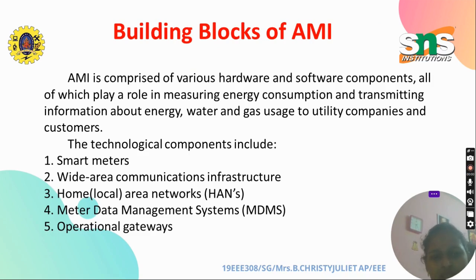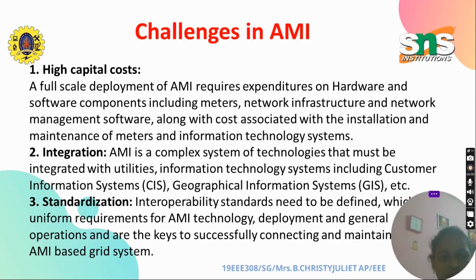Now, what are the building blocks of AMI? AMI is composed of various hardware and software components, which play a vital role in measuring energy consumption and transmitting information about energy, water, and gas to utility companies and consumers. The technological components include smart meters, wide area communication infrastructure, and of course, to have two-way communication we need HANs, which are home area networks like LAN, and we have meter data management systems (MDMS) and operational gateways.